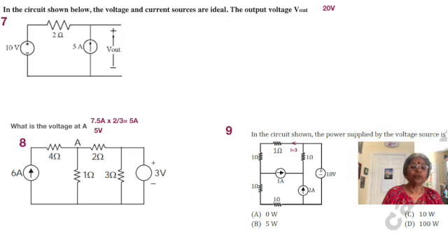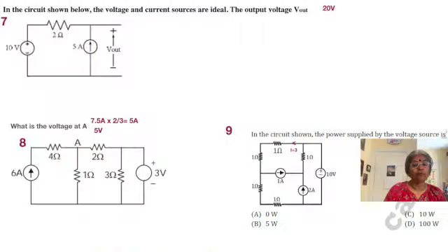So what is asked is what is the voltage at A. We see that there are two current possibilities there. One is of course that the 6 amps and the 1 ohm together give rise to 6 by 1, that is 6 ampere, to node A. At the same time, after removing the 3 ohm resistor in parallel to the 3 volts, we have another current source where the 3 volt and the 2 ohm in series with it together give rise to another current source equal to 1.5. So together, two types of current sources come together at A, and that's equal to 7.5 amps.